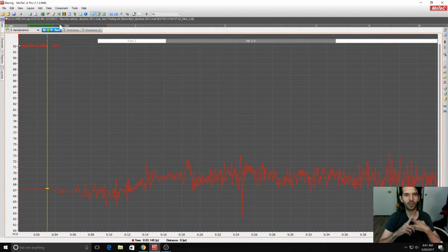Then after that, we're going to do our aero test. We're going to speed up to 150 kilometers an hour. 60 because there really shouldn't be any aerodynamic load on the front of the car or the rear at 60. So if we assume that the aero is negligible at that point, then we can assume that the suspension is as high as it should be. We're at constant velocity, so we'll zero it there. Then we'll speed up to 150. Then we'll hold that for a few seconds.